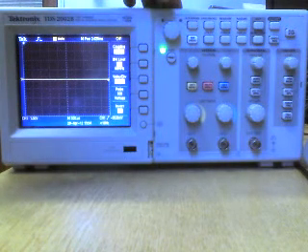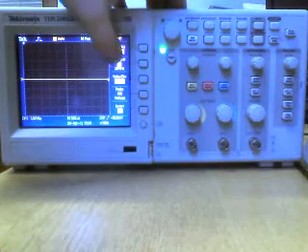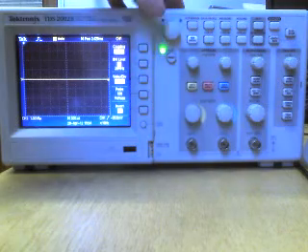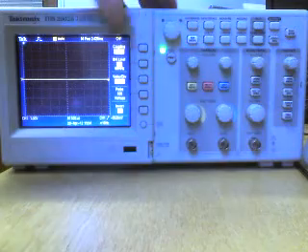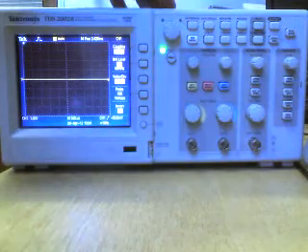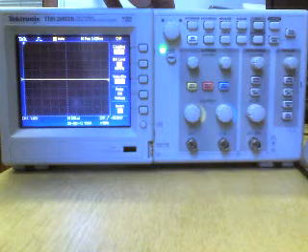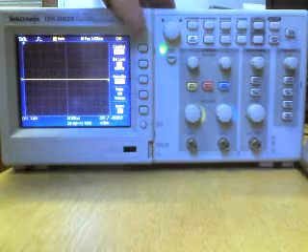And also, if you've got particularly high frequency noises and whatever, you can actually switch that on. Anything above 20 meg as opposed to anything above 60 meg gets attenuated out, so you can actually clean up your signal as well. But normally leave bandwidth limiting off. Within the lab, within your first year or two of your degree here, just have it off. It's not really going to make that much difference to what you're going to be doing.